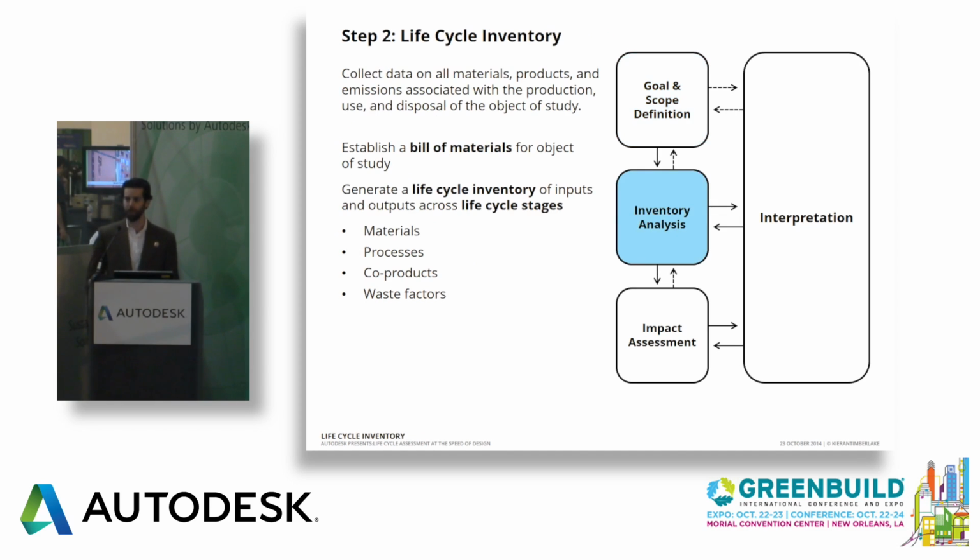So let's say once you've done that, and you've done that over the scope of your entire building, you want your scope of assessment might be a whole building assessment, say, and you realize there's a number of materials that have different lives in them, and each one of them will have sort of its discrete functional unit. The key then is you have to figure out how much stuff you have in the entirety of your building. So you really have to answer the Bucky Fuller question of how much does your building weigh? And the second thing, of course, with that is you have to know what is the impact associated with the manufacturing, maintenance, useful life, and disposal of all those things that you just went out and weighed.